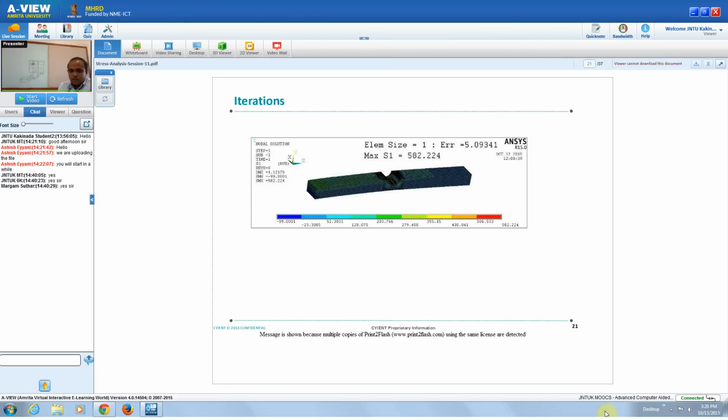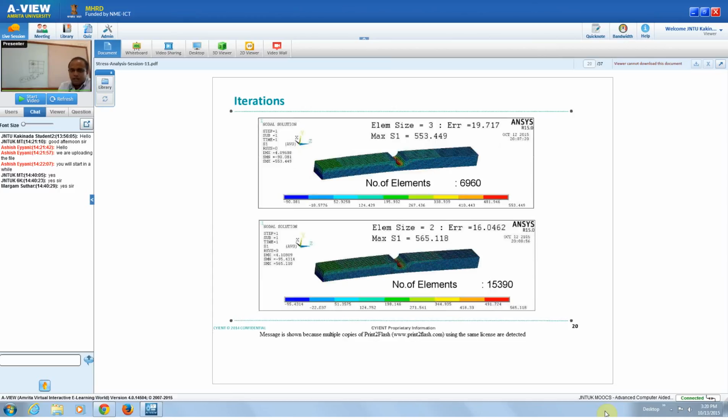But here, maybe your picture is not clear. You can see the high critical stress is happening at the ID of the bolt hole. So we are getting high stress at this location. Instead of putting mesh everywhere equally, we can make a cut here and put a fine mesh here, with a very smooth fine transition mesh.